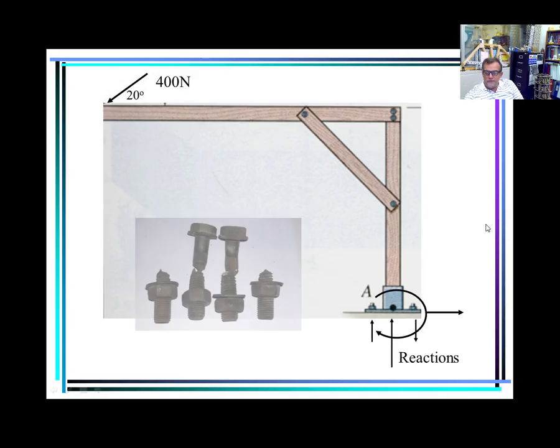So look at those bolts, for example. Of course, those are not from this example because this is a theoretical example, but if these bolts were somewhere to be found here in this part, look, what happened in that bolt is that when this was pushed in this way, for this not to fall in this way, basically this bolt here was holding it in place, and that bolt stretched, and the stretching of that bolt could cause this type of failure.